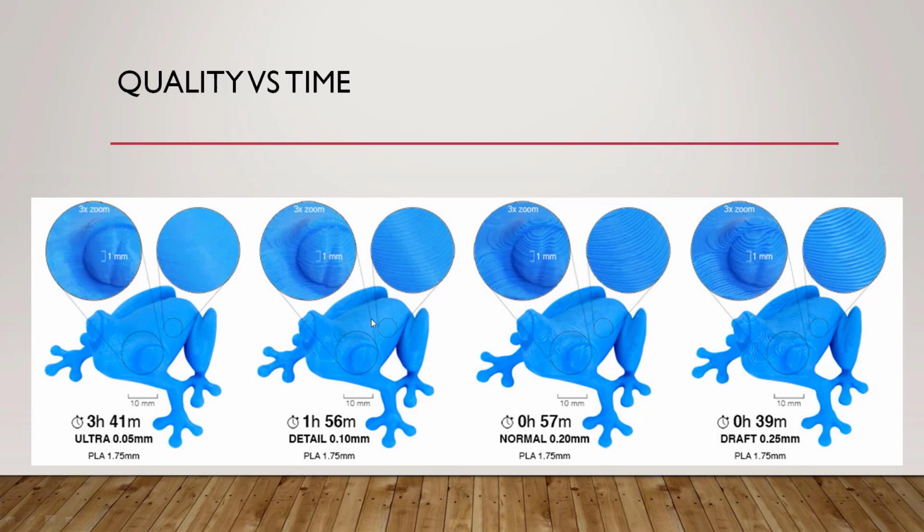If I talk about layer height versus time, it means quality versus time. If layer height is low, then your quality will be high and the time will be more. So in this left hand first diagram, you can see this is taking 3 hours 41 minutes. This is ultra high finishing. Here the layer height is 0.05 mm and taking PLA material. If you zoom in, you can see the fineness of this.